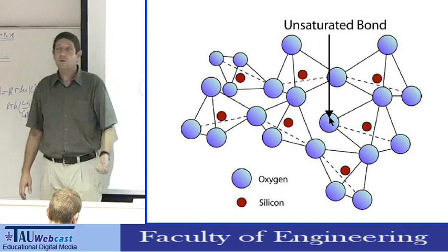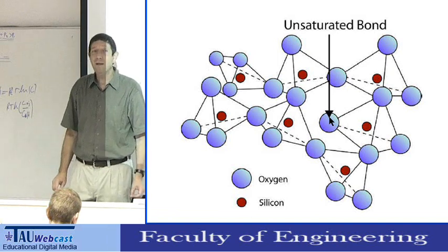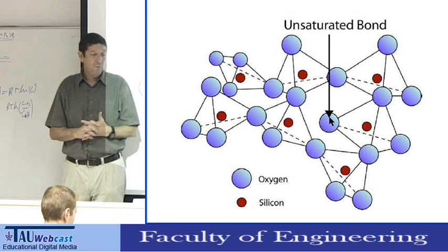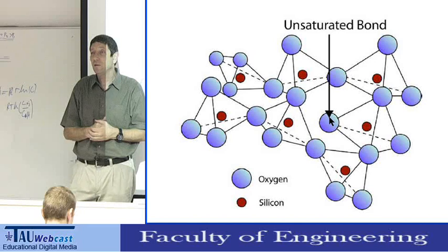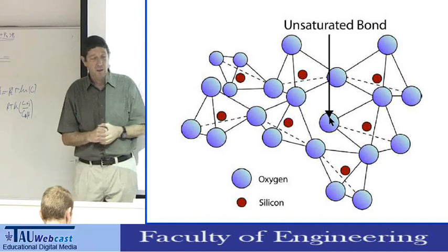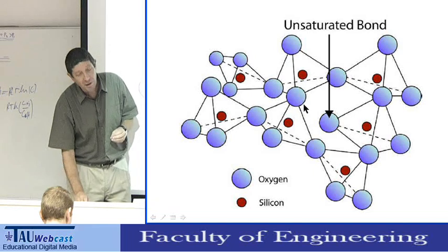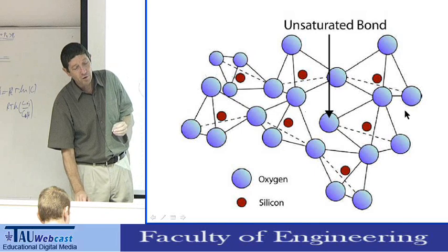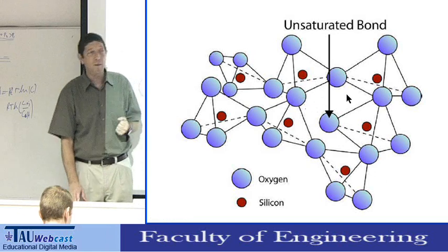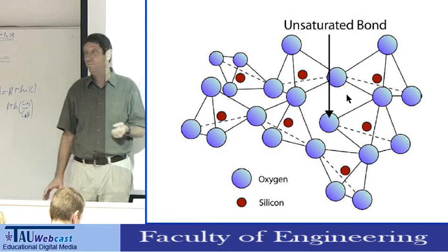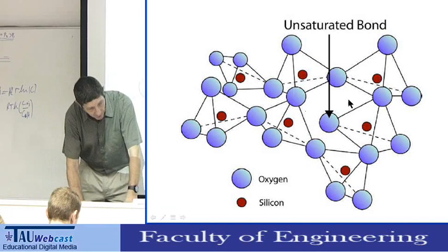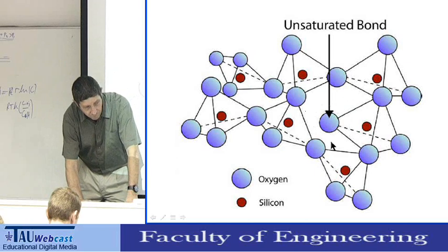Now, the actual structure of the silicon dioxide also depends on the doping. If we add some doping into the glass, to the SiO2, we can affect the properties. However, we usually deal with very highly pure oxide, and there is not so much doping in normal situations. But you can think about some contamination. For example, if you have sodium. Sodium atoms, Na plus, are very, very small, and sodium can form an ion, and the ion can affect the